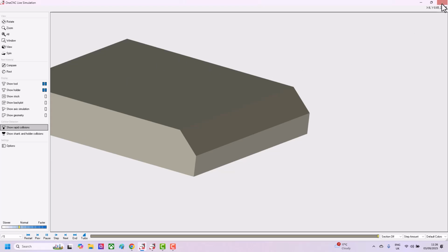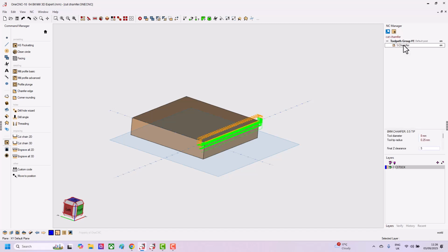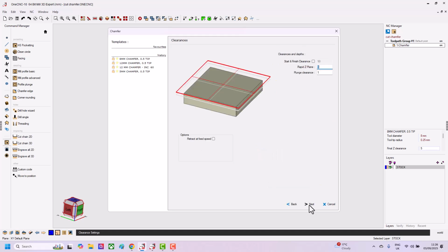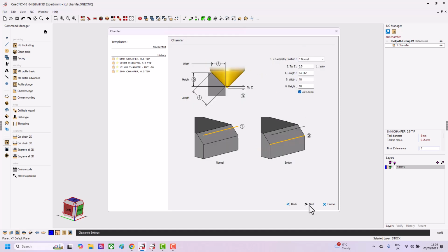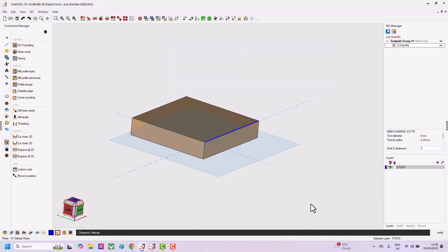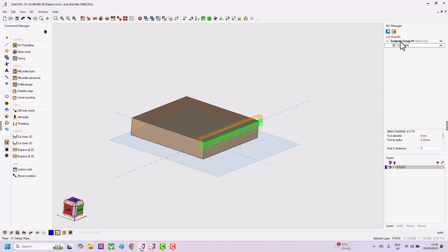So let's just go in and change a couple of these settings. We'll go into edit. Let's say we thought the radial cut was a little bit gentle. So we're just going to untick the automatic. We'll say a step over distance of 1. We'll leave everything else pretty much the same, and we'll accept the form all the way through. And we can then right click and simulate.